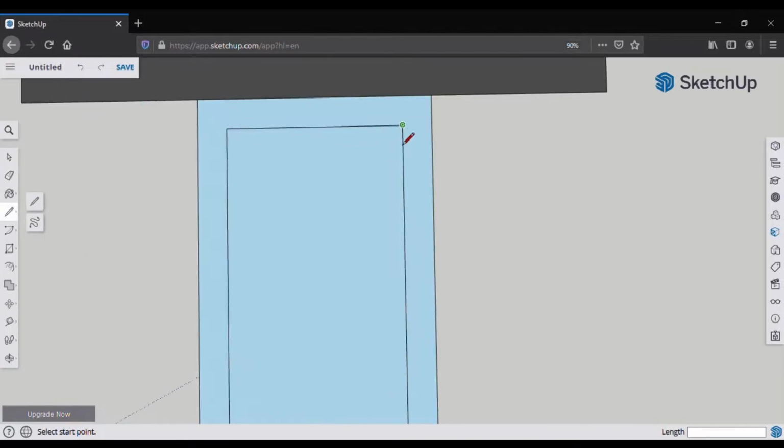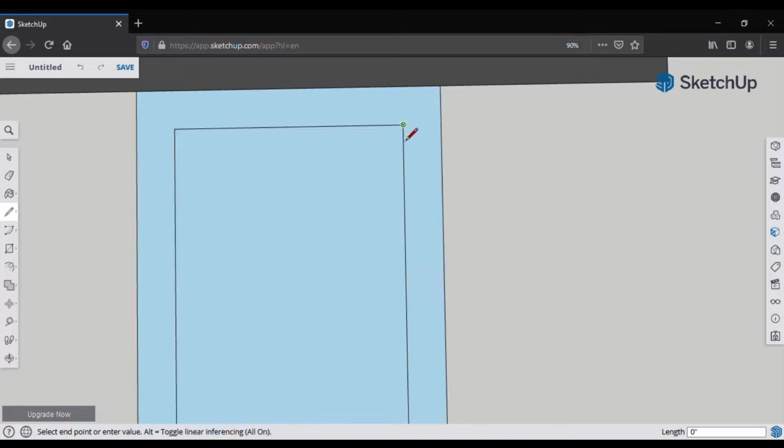I'm gonna make this rectangle a house. First I'll make walls which will be 10 inches. One thing to understand, if I simply write 10 without a unit, then it's automatically in inches, although I can still use the inverted comma for inches, but it's just time consuming. So I'll write 10 from the point to the next possible place.